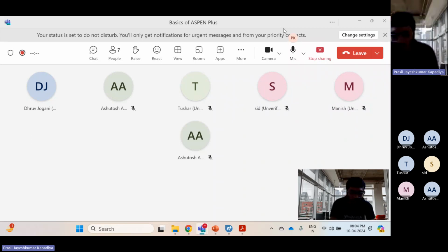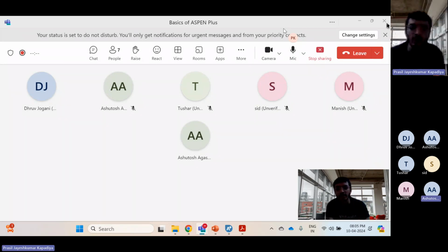If you wish, you can play with some convergence criteria, like we did today. We changed it from the default to Newton's method. You can try something like that. Anything other than that won't be useful. Everything is correct. You just need to play with the convergence criteria only. In today's lecture for the ammonia problem, we changed it from the standard default to Newton. You can try it with that. If it works, it works.